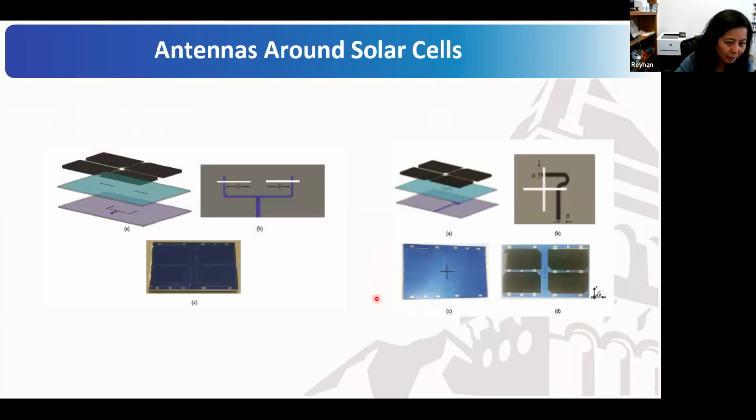I thought I had some design curves, but anyhow, I'll just show you the prototype design. This is a circularly polarized cross dipole, a very easy circular polarization method just by bending the feed line to create the 90-degree phase shift. And this one is a linearly polarized antenna, but we designed the spacing such that this antenna can be made into dual band. So you can design one set of antennas for uplink and downlink, etc.